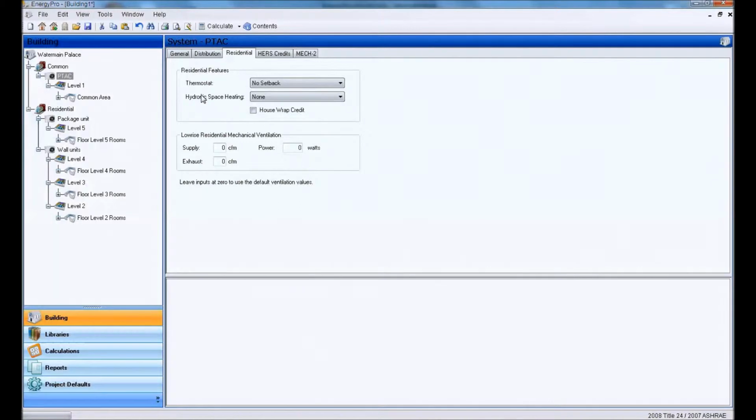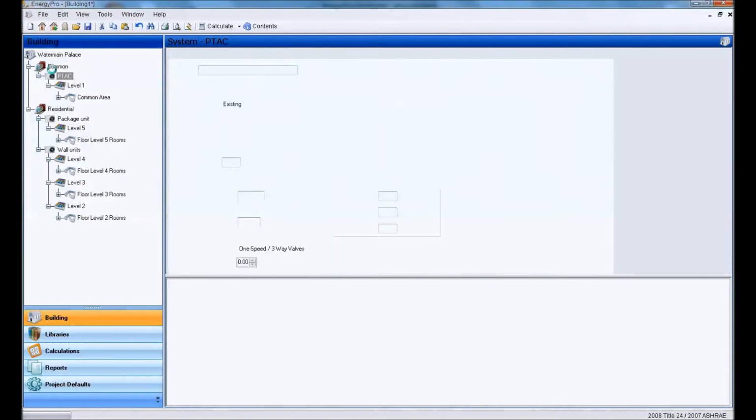drop down icons. The hydronic space heating drop down is only if we have a boiler that is providing us with hot water or steam for our system. So if it's a boiler that's providing hot water, we will say that it's a heating boiler that's providing the heat. And if it's a hot water tank, like an indirect storage tank from a solar tank, or even if it's just a water heater that's providing the hot water in an open loop system, we would say that domestic hot water is providing the heat. And that's related to our plant icon.